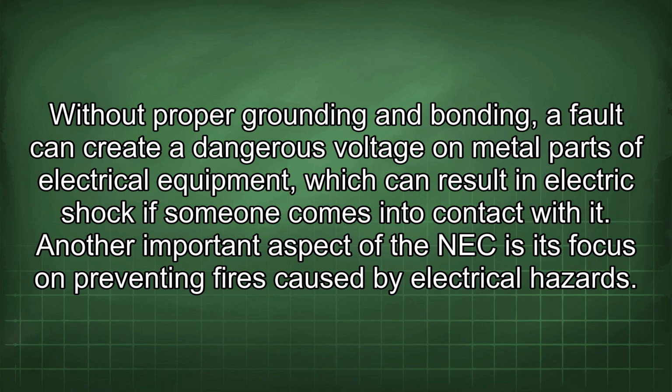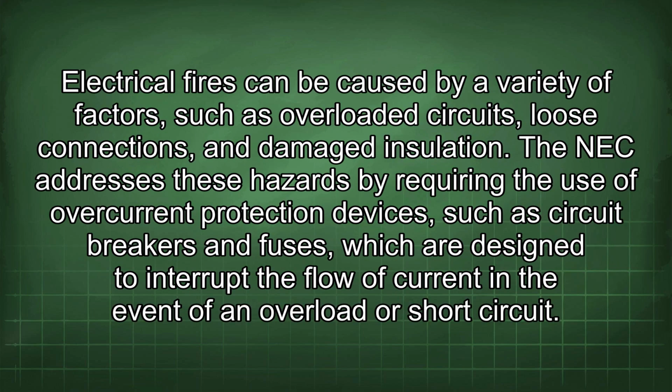Another important aspect of the NEC is its focus on preventing fires caused by electrical hazards. Electrical fires can be caused by a variety of factors, such as overloaded circuits, loose connections, and damaged insulation. The NEC addresses these hazards by requiring the use of overcurrent protection devices, such as circuit breakers and fuses, which are designed to interrupt the flow of current in the event of an overload or short circuit.